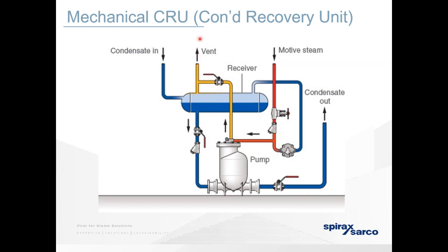Now this vent will go through a wall or a roof space, and you'll see steam whispering out of the top of it. That's what we call flash. We can recover that flash because it's still energy, it's still steam, be it at a low pressure, and we can use it elsewhere in your process. A perfect example would be running, say, a small heat exchanger for hot water in a bathroom or a washroom.